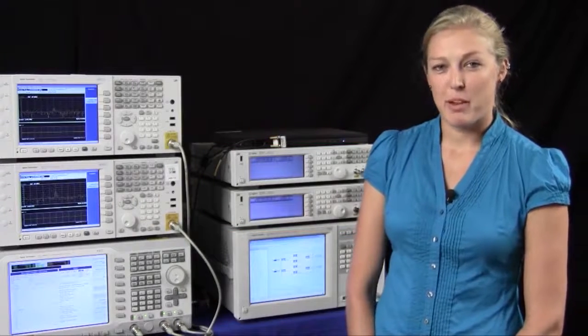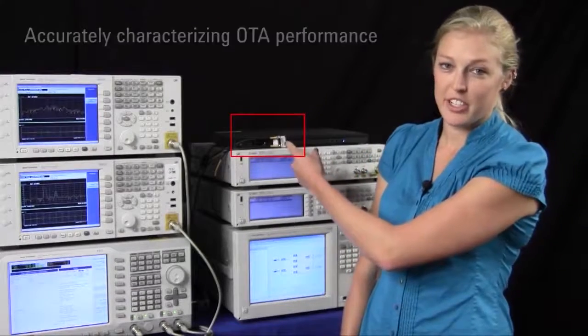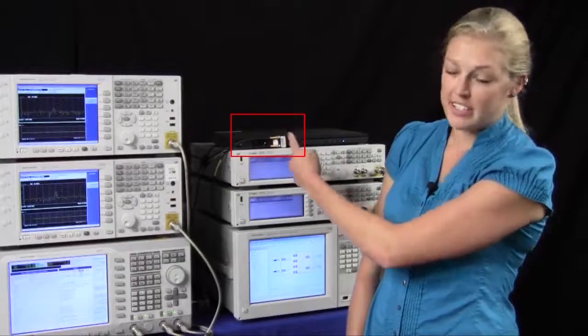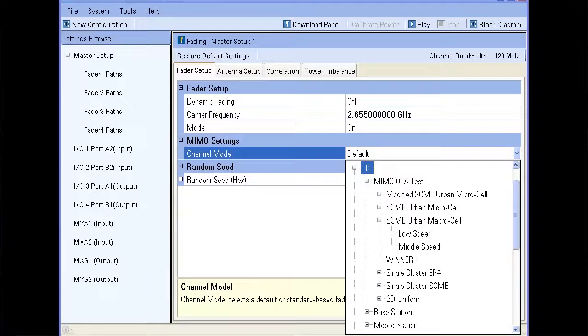Since the antenna gains have already been applied, we're accurately characterizing the over-the-air performance of our device through our cabled connection here. The uplink signal from our device is then going back to our PXT where we can measure the physical layer throughput. There are several LTE channel models specified for MIMO over-the-air test, which replicate real-world MIMO conditions and channels and generate realistic fading scenarios including path and channel correlations. The PXB emulates these channel models. In our demo, we will be using the SCME urban macro cell model. The PXB is also digitally applying the antenna gains from the antenna pattern generated in stage 1.